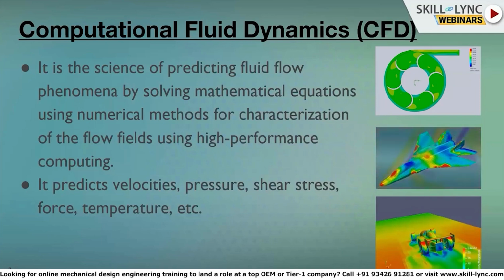So in those scenarios, we go to numerically solving these governing equations using a computer. Basically, this you might be knowing, but still I will give a brief introduction. We discretize the fluid domain or the problem domain, and we approximate the partial differential equation to algebraic equations, and we solve for each cell in the discretized domain.